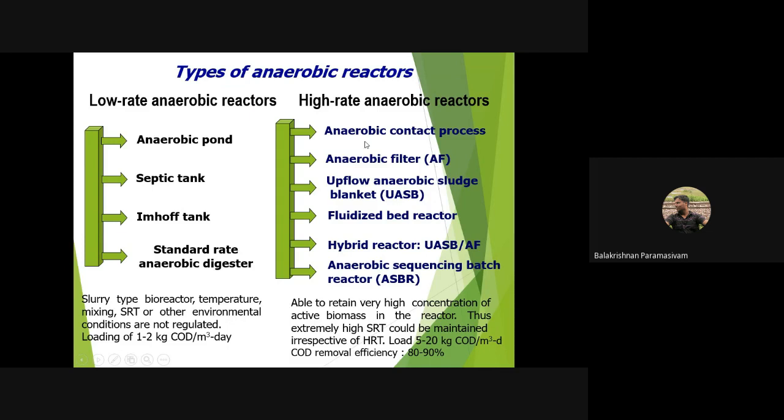So I will be going to discuss anaerobic filter, upflow anaerobic sludge blanket, fluidized bed reactor and hybrid reactor. So these 4 reactors are conventionally followed for industrial as well as domestic wastewater treatment systems. So in this we can remove up to 80 to 90% of COD. Generally, an aerobic treatment process is designed based on the biological oxygen demand, while an anaerobic treatment process is designed based on the chemical oxygen demand. So this we need to understand while designing any treatment system.